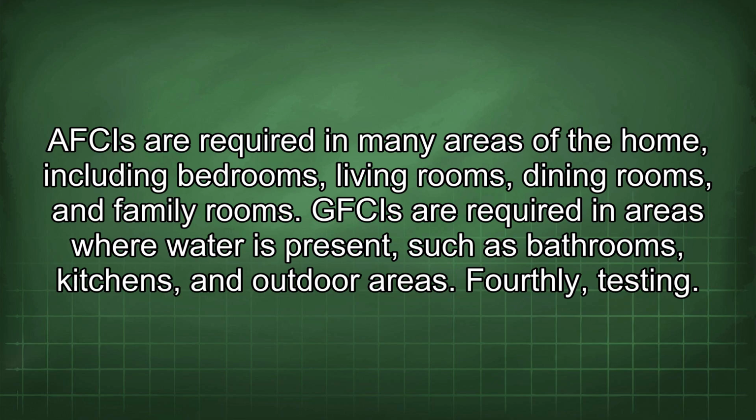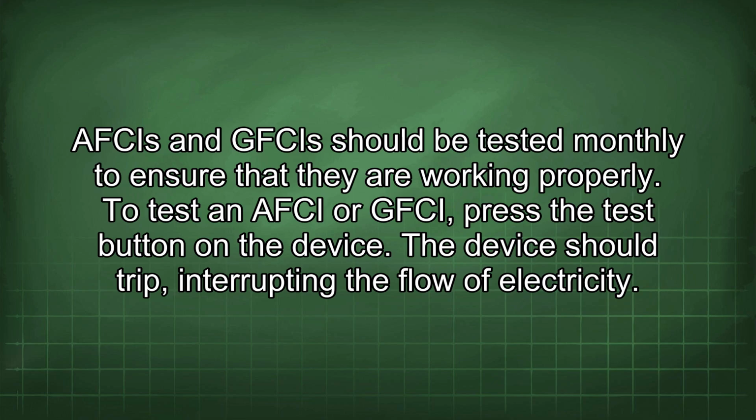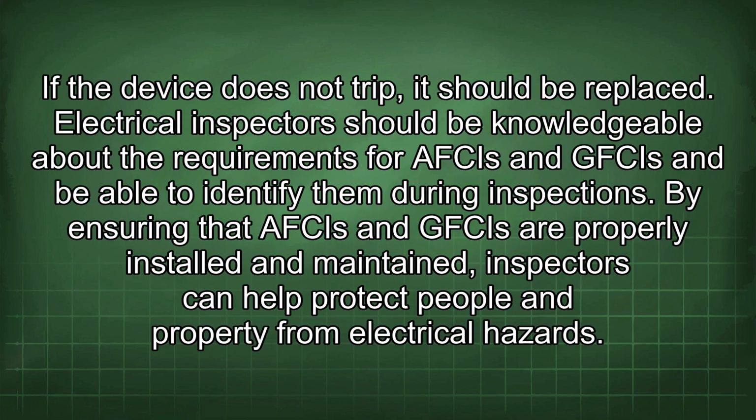Fourthly, testing. AFCIs and GFCIs should be tested monthly to ensure that they are working properly. To test an AFCI or GFCI, press the test button on the device. The device should trip, interrupting the flow of electricity. If the device does not trip, it should be replaced. Electrical inspectors should be knowledgeable about the requirements for AFCIs and GFCIs and be able to identify them during inspections. By ensuring that AFCIs and GFCIs are properly installed and maintained, inspectors can help protect people and property from electrical hazards.